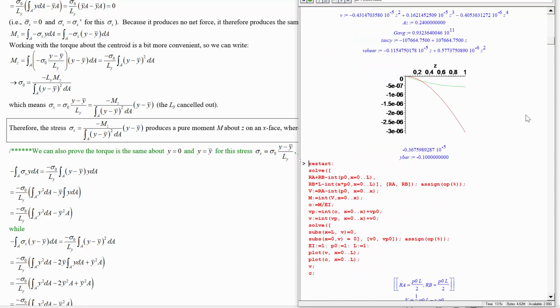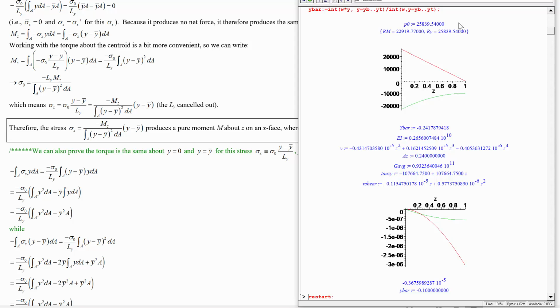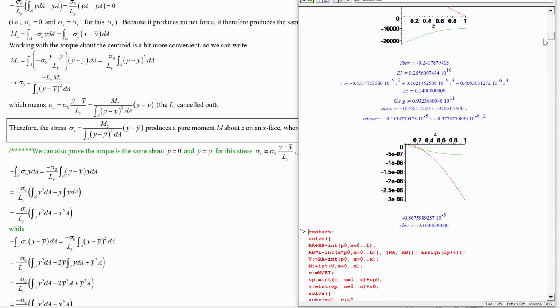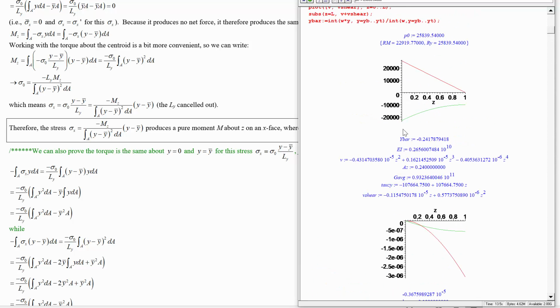That was a missed opportunity. We should think about where that is. It should be pretty far into the tungsten, right? So it's negative 0.24. Yeah, it's almost at negative 0.3. And that should be lower down than the actual y bar, the one that's just weighted by area. This one is higher up because it's not as influenced by tungsten's superior Young's modulus like big Y bar is.